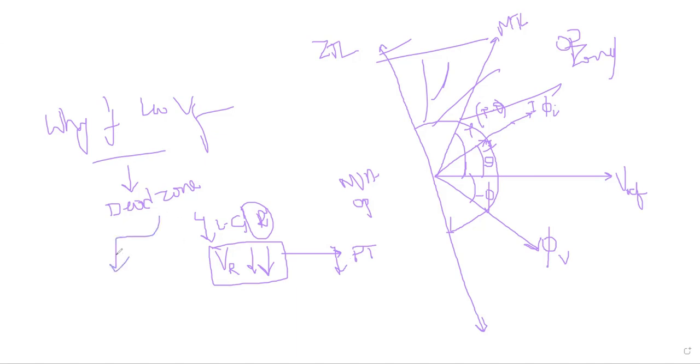What was generally recommended is the V reference, the polarizing voltage I explained, right? This is the voltage we generally consider. Suppose an R phase fault occurred, we will take the R phase current and compare it with the Y and B phase voltage. This Y and B phase voltage will not be collapsed, so we take this voltage as a reference.